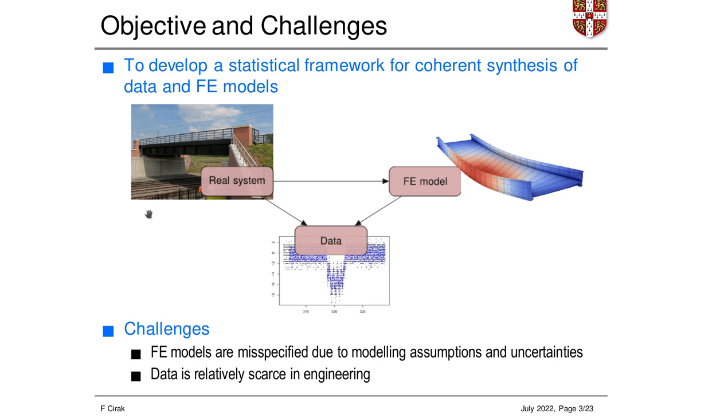Here is a real-life example of a bridge in the UK. This bridge serves as a real system. By placing some sensors at some locations of this bridge, we can collect measurement data, for example, strain data, and we have a finite element model of the bridge. And the objective is to make finite element predictions conditioned on the collected data.